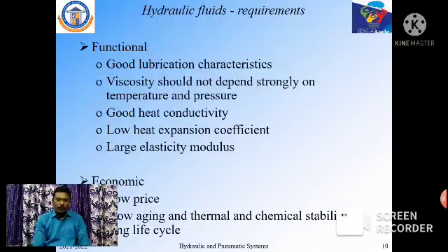Hydraulic fluid requirements. Functional: good lubrication characteristics, viscosity that does not depend strongly on temperature and pressure, good heat conductivity, low heat expansion coefficient, large elasticity modulus. Economics: low price, slow aging, thermal and chemical stability, long life cycle.